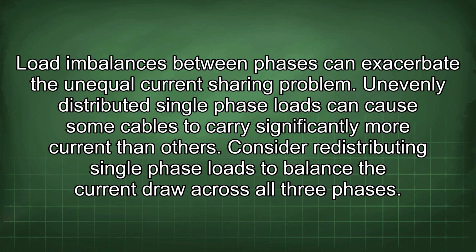Load imbalances between phases can exacerbate the unequal current sharing problem. Unevenly distributed single-phase loads can cause some cables to carry significantly more current than others. Consider redistributing single-phase loads to balance the current draw across all three phases.